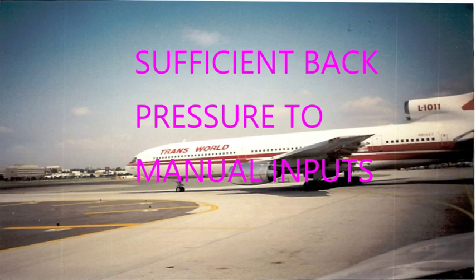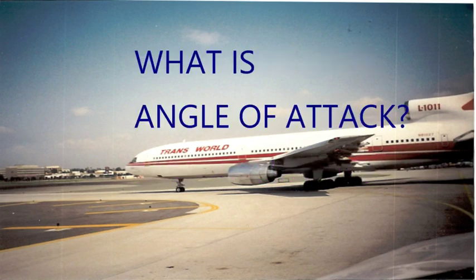Okay, number two, you remember angle of attack. What's the angle of attack? Let me define it. Your angle of attack is the angle between the chord of an airfoil, which gives you a reference line, and the direction of the surrounding flow of air. So that's the angle that's there. And again, if you really wanted to get into aerodynamics, we could get into detail on theta and beta and all these different angles that are defined when we talk about relative wind and the airflow around the various parts or components of the aircraft.